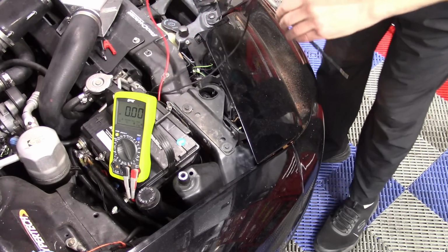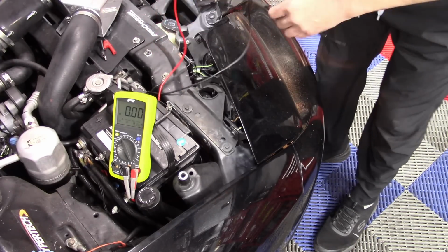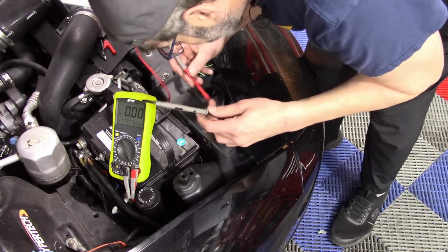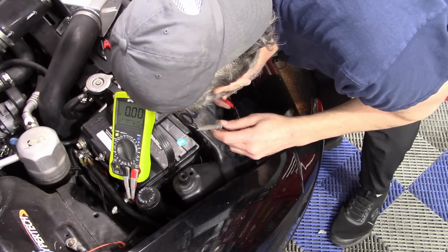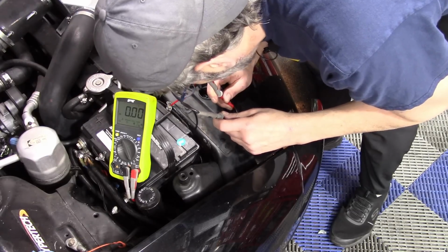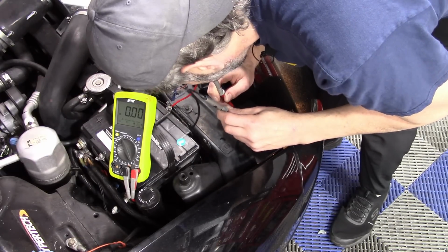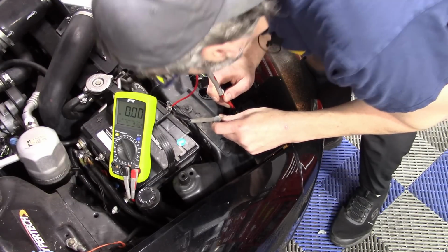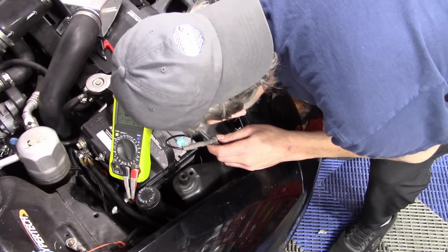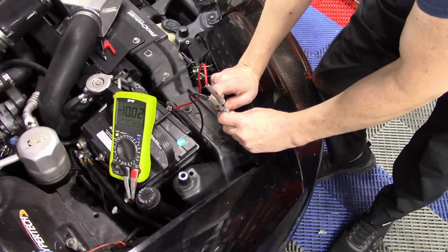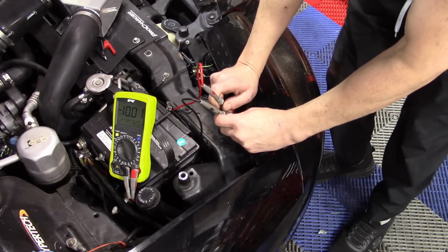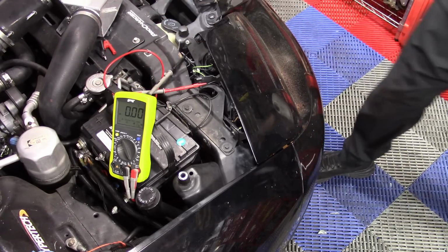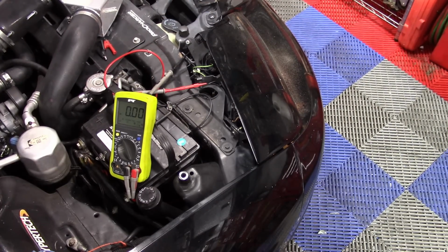Another way we could have determined that the brown wire is positive and the black wire negative is the fact that we saw a positive reading. If I switch around and put my positive lead on the black wire, whatever that is, and my negative lead on the brown wire, we now get a negative 10. What that means is my leads are reversed and the positive lead from my DVOM is on the ground. So that's another way I can identify my wire colors here.